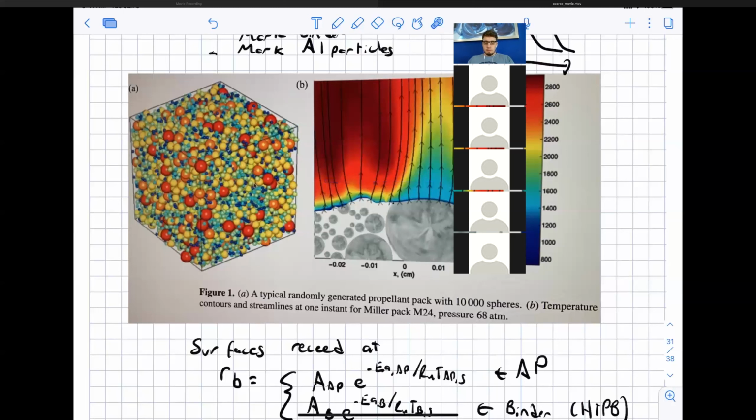And so that's also why, because of that dimensional simplicity, you start to see people simulating erosive burning and things like that with homogeneous propellants, or they'll do one-dimensional simulations with, say, 400 chemical reactions. Because they're known for homogeneous propellants, are known well enough. And also you're just doing the simulations in 1D, so it's practical to do that. Okay, but in general, because the flame structure for a heterogeneous propellant is not truly one-dimensional, they are much more expensive.